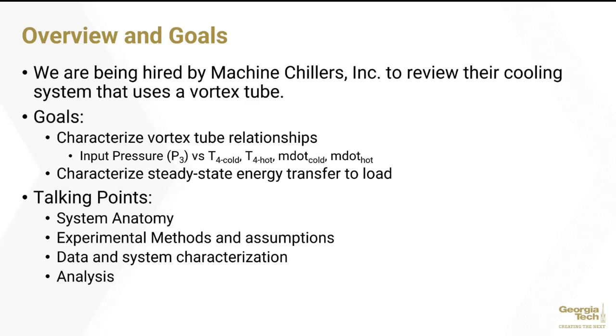The goals of the previous week's lab was to characterize the vortex tube's relationship between input pressure, denoted as P3, versus T4 cold and hot, and M dot cold and hot. The origins of these properties will be talked about in the next slide.